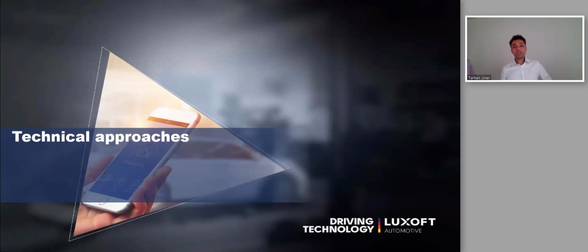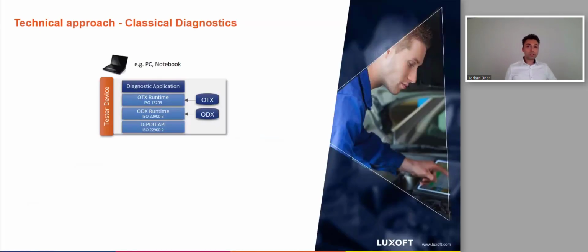So let's now move on to technical approaches. Let's have a look into the old-fashioned classical diagnostics. Gladly, nowadays, we have a laptop or a notebook where a diagnostic tester is running on. The diagnostic application has all the diagnostic knowledge. As an example, all test sequences, all information on how to read data out of an ECU, or on how to control actuators within an ECU. But that's not enough. All those information needs to be interpreted. A diagnostic application needs to know how to communicate with an ECU.